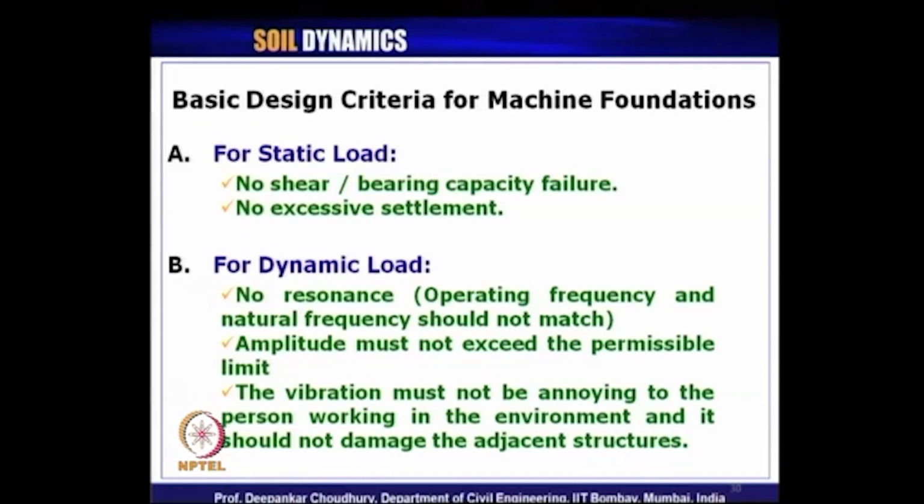So, remember, the natural frequency has to be calculated for the entire system, not for the foundation only. This is an important point, because of the consideration of which mass you should take: the foundation mass or the foundation mass plus the machine mass. That is what you should take, right. The second one, to calculate the natural frequency, to avoid the resonance. So, they should be far away from each other.